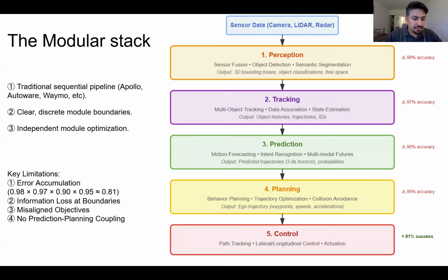Then sensor fusion itself used to be, we got individual sensors, and then we used to have the tracking or the smoothing run on the individual sensors and then fuse them together. But now it's early fusion systems that we are seeing coming up overall, which are able to take the raw data from all the sensors and in one shot generate the detections, the classifications, and the predictions. So that is one side of the stack.